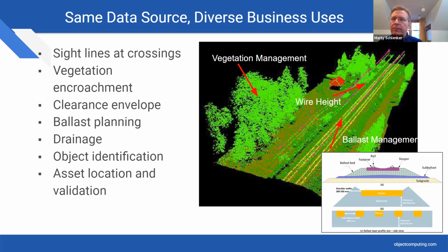Curves will walk, if you will, they'll push out over time with tonnage, especially if the ballast section doesn't sufficiently hold the track in the curve, or if the super elevation and the prevailing speed of trains is unsynchronized somehow. So it's not just the environment around railroad tracks that moves, it is also the railroad tracks that move themselves in minute but sometimes important measures.